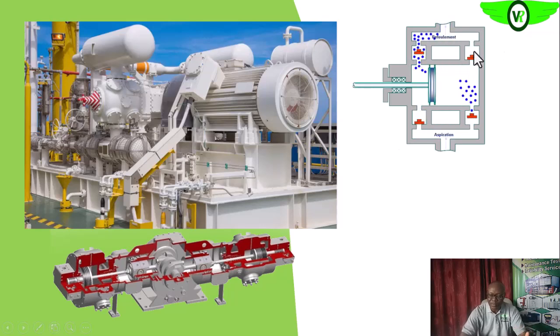That will help to stabilize the pressure, unlike when you are using a single acting reciprocating compressor, where the pressure at the discharge will be pulsating. With a double acting one, the pressure will be a little bit stabilized. Are we getting it? It could be discharged into a vessel to stabilize the pressure before you send it into your process anyway.